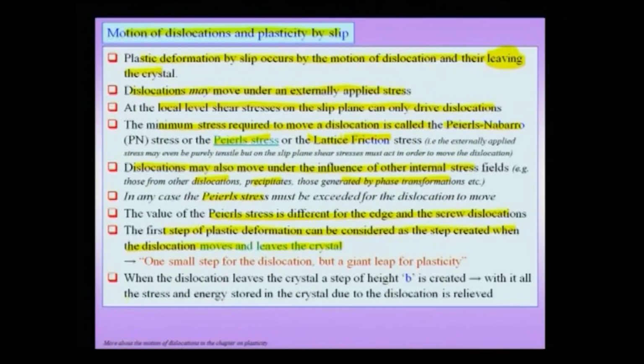Now, it is important to note that this is one small step for a dislocation, but a giant leap for plasticity, because this small step which we are considering here lies at the heart of all plastic deformation. When, as I pointed out, even this dislocation leaves the crystal, a step of height b is created. With this, all the energy and stress stored in the crystal due to the dislocation is relieved, and therefore now